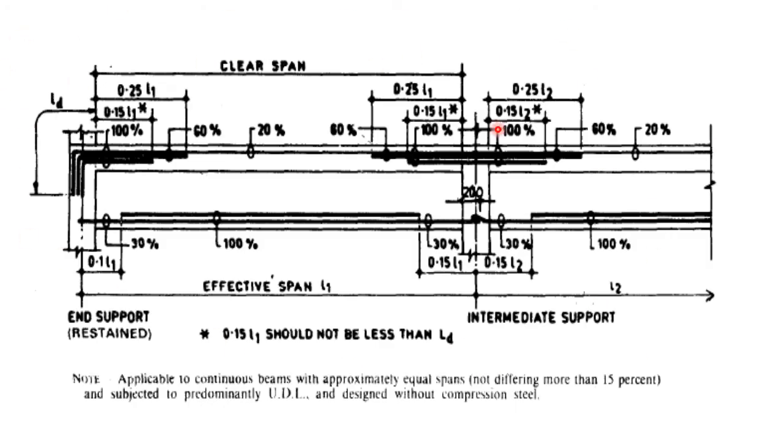This diagram will give you completely the details of longitudinal reinforcement. Now, before I go to that, one thing we should make clear: whatever span they have given, it will definitely be a clear span, that is from the outer face of the supports. So to calculate the effective span, you have to take half of the support width plus clear span plus half of the support width, which will give you the effective span. And as I already told, for a continuous beam, the number of spans should be more than 1.